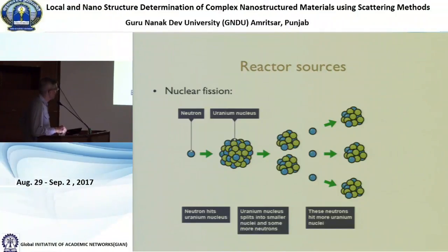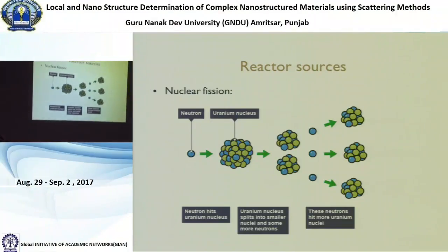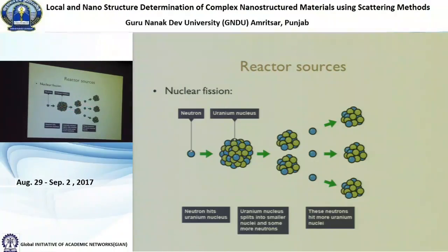And in order to ensure that it happens slowly, you have control rods which selectively absorb the neutrons. So you control the neutron flux inside the core with these control rods, and you put the control rods in and out. And you can have a disaster like Chernobyl if for some reason the rods are pulled out and the reaction starts going too quickly and you don't put the rods back in quickly enough. Most modern reactors are designed to be fail-safe, but there can still be accidents.